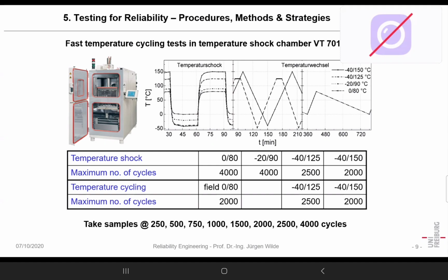No. On the other hand, when I dip it in liquid nitrogen, for example, what will happen then? The outside is extremely cool. It will contract, and that will lead to compressive stresses inside, but the outside layer has tensile stresses. And tensile is often bad. It can crack just as a result of the speed of temperature change.